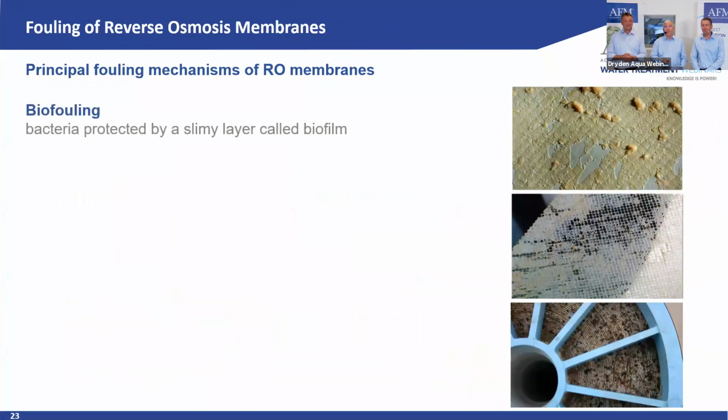So biofouling is one of the key, we talk about that constantly now. Biofouling is the biggest critical problem in membrane systems. You can see here a membrane which is biofouling. You can see really that's an additional layer on the surface which provides for some very bad operation of your membrane system. Looks a little bit like the sand that we showed before, right?